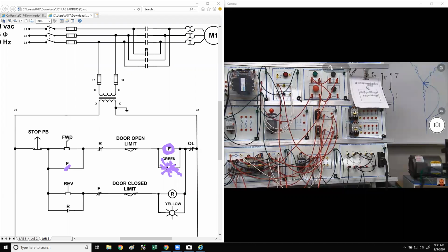That means when you press this button, you're getting 120 volts and current going through that light. So where does the problem have to be? Either in the contacts or in the coil. If it's not pulling in, well, no, it has to be the coil. The green light is turning on, so you're going to look right here. That narrows it down quite a bit, right?